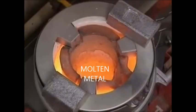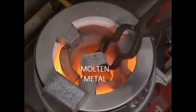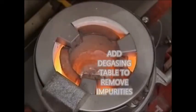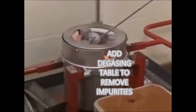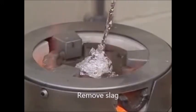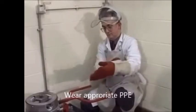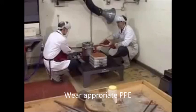Preheat the ingots of aluminium before placing them in the crucible. The temperature of the melt should be established using a pyrometer. A degassing tablet should be added to remove impurities. Any surface slag should be removed with a preheated rake. The melt should only be poured by trained staff wearing the appropriate PPE, including substantial footwear.